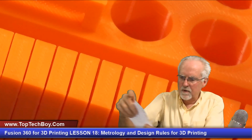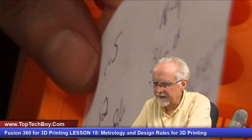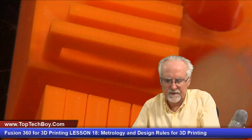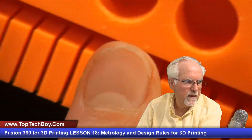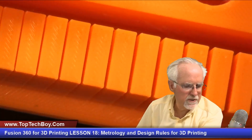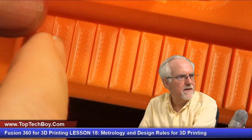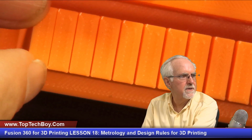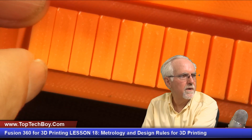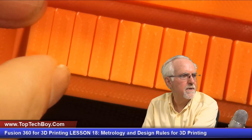In fact, I could probably slip a piece of paper down in there. Yeah, you see I've got a piece of paper that I can slip in that gap, so I know that gap is really there. And as I look at it, I'm not seeing any bridging. Now, the interesting thing, which is even more of a surprise to me, is that it is really close to getting a 1/10 of a millimeter gap, but I am seeing bridging here on the corner. And you can see the bridging almost happened here on the corner, but the gap is still open.